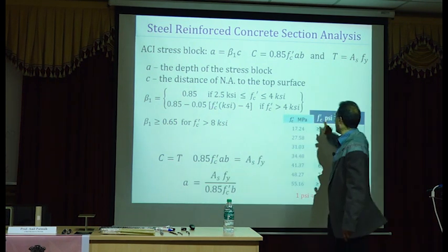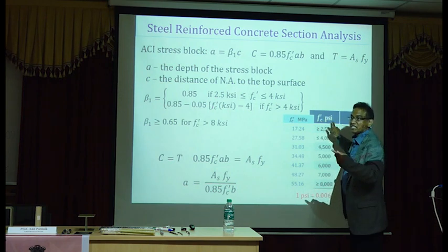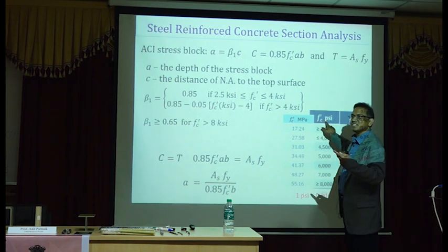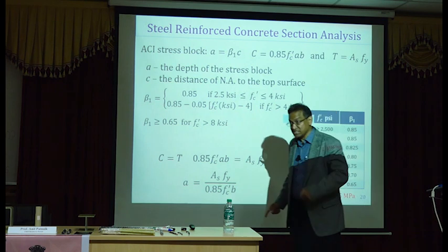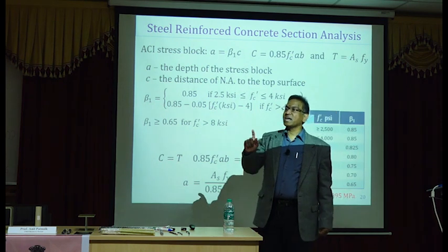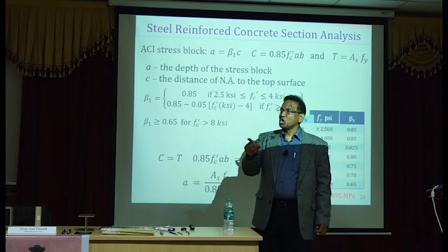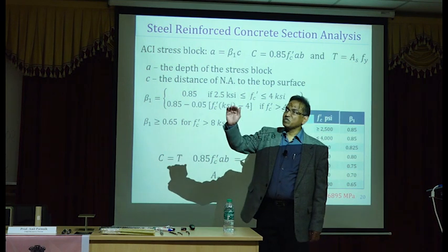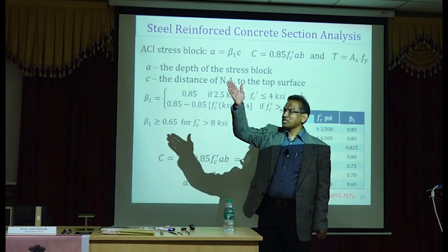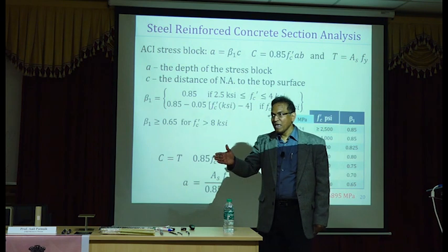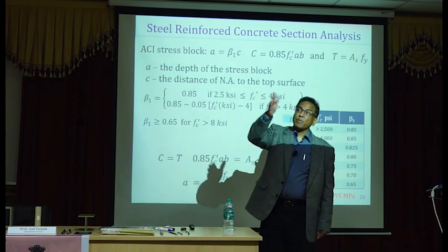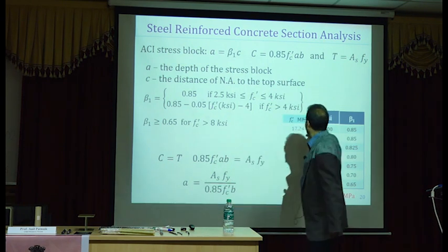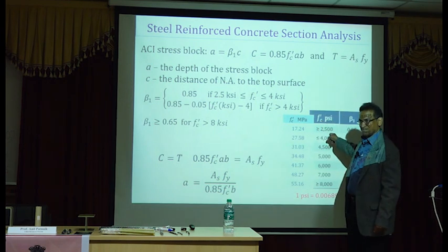So this is your design value. Just like your characteristic value, this is the design value. ACI is not considered as quality? Yes, they do. But what they do is they're asking the supplier to make a concrete which will have a statistically larger mean, so that when you supply to the site, we have a guaranteed compressive strength of whatever this is.